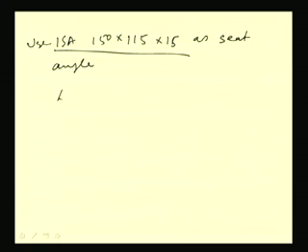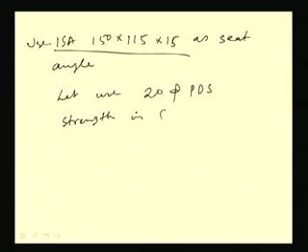Now, select 20 mm diameter of power driven shop rivet. So the strength in single shear will be, because we have to find out the number of rivets.